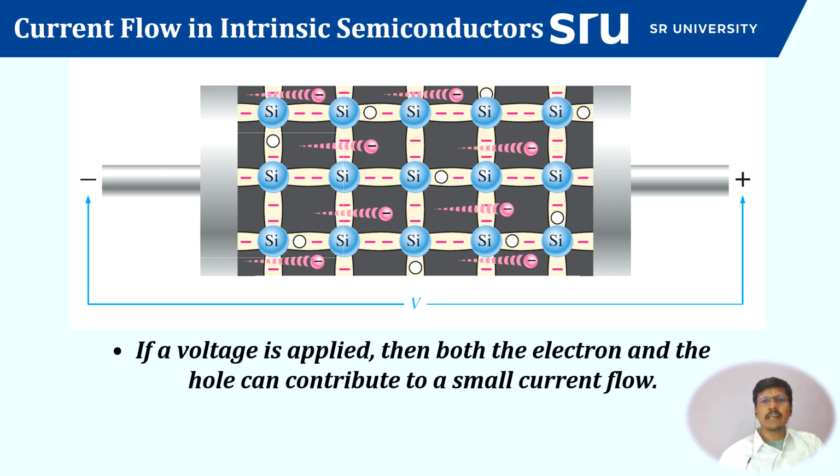This analogy helps to understand why hole motion contributes to the current flow. The simultaneous movement of electrons and holes enables intrinsic semiconductors to conduct electricity despite being composed of neutral atoms. Understanding this visualization is essential before studying doped semiconductors and p-n junction diode devices.